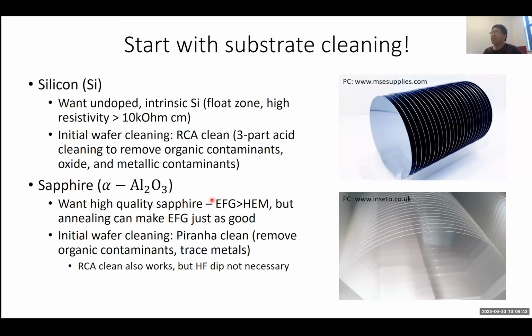So is there any references on this annealing process and a documentation of what it does and what kind of a good effect it does? So there are several papers that talk about sapphire annealing for the purposes of surface reconstruction. To the point where if you do AFM on the surface of the sapphire, before and after annealing, you can clearly see a difference where after annealing, you can observe monoatomically flat surfaces and things like that.